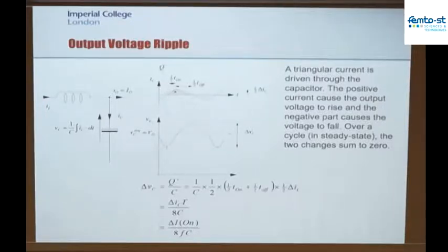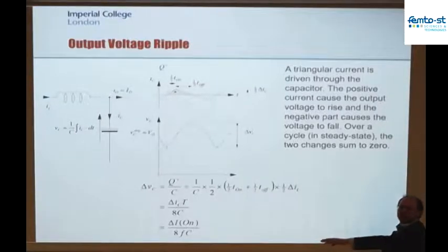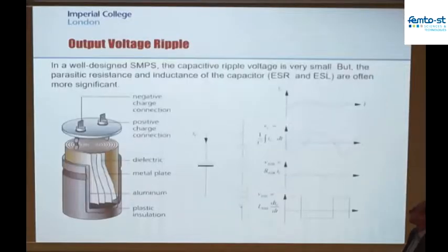So I've got a circuit topology here which is inherently much more efficient than the linear regulator circuit, but clearly has quite a few more quirks than the linear regulator. This requires me now to have a small voltage ripple on the output. On the previous circuit, I could get something that was dead level, perfect DC output. This one is almost a perfect DC output, but with a small ripple on top. And if I operate the circuit at higher frequency, or I put a bigger capacitor or a bigger inductor in, I can reduce the value of that ripple, but it's always going to be there.